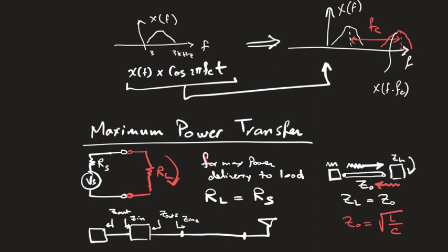If you choose components with different input and output impedance from each other, then this system is not going to be efficient and it's going to malfunction after a while because of the heat built up in the different components due to reflections. Okay?